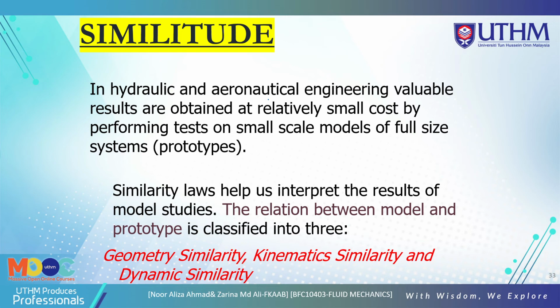In hydraulic and aeronautical engineering, valuable results are obtained at relatively small cost by performing tests on small scale models of full size prototypes, or the system is called the prototype. So similarity laws help us to interpret the results of model studies. The relation between model and prototype is called